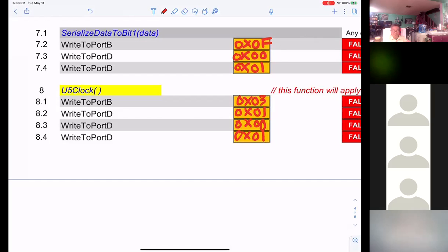That means you load number 9 into U4, and you look at the segment display: number 9. You load number 3 on U4, and you see number 3.